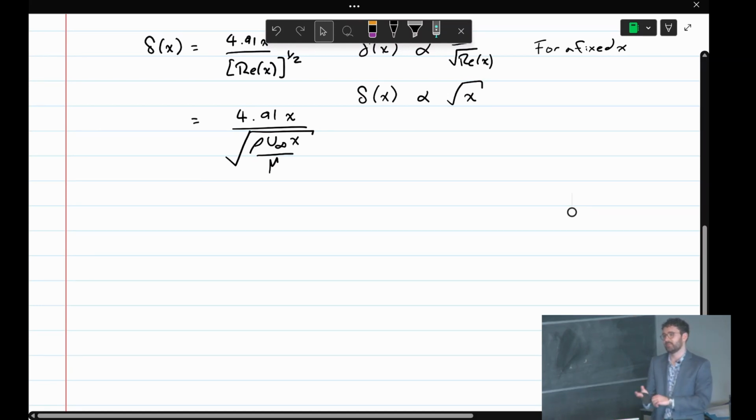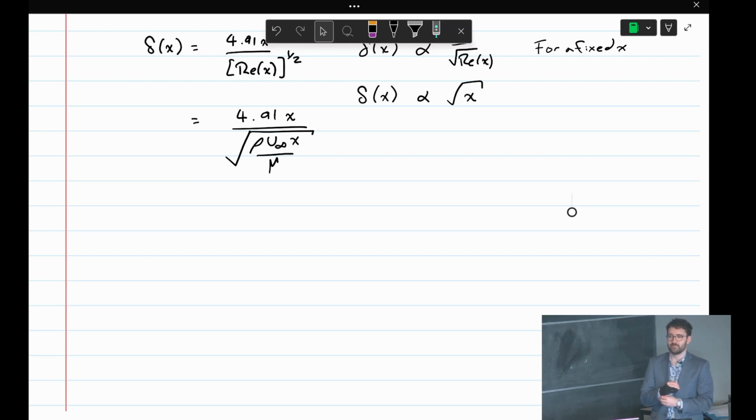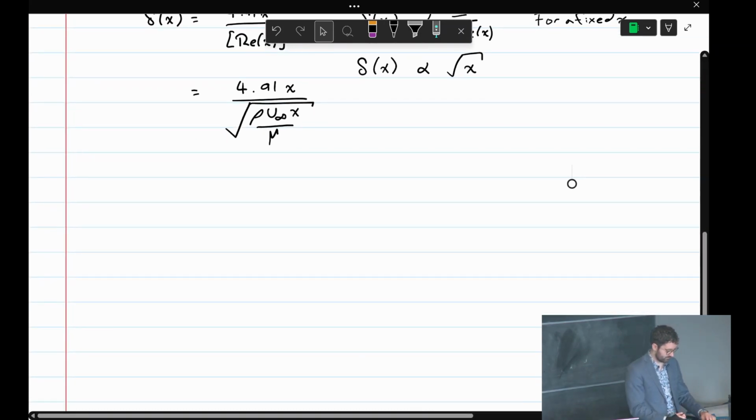Yep. Once the oscillation starts, once the vortex shedding happens, it will just go on forever. It's self-sustaining. The energy input to that is all coming from the free stream, so it's not going to damp out or anything like that. There's probably some sort of energy balance that has to happen between the dissipation due to viscosity and the energy that wants to do that unstable motion. Okay, so